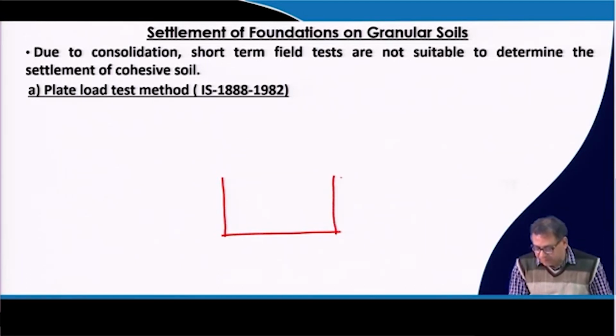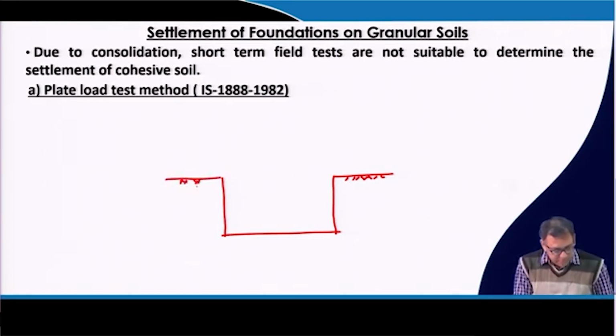At that depth we have to conduct the plate load test, and the depth should be equal to the depth of the foundation. Okay.